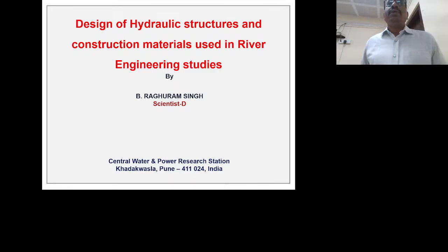Yes, good afternoon. For the last 3 days, we have learnt about the design of hydraulic models and mathematical models. First, I explained how to design a physical model. In that, I explained how we decide the geometrical scale and distorted scale, and which geometric scale is used for which type of structures, like spillway modeling, reservoir sedimentation, and flushing type of hydraulic structures.